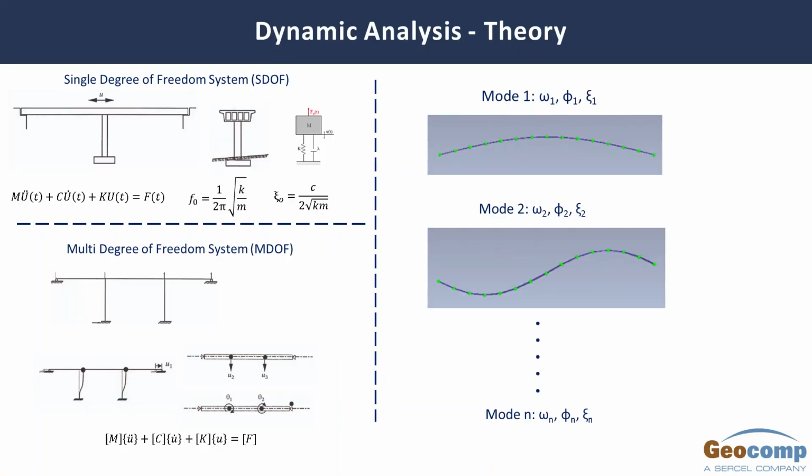So what we do, now we are going into the observation phase, the field testing phase. What we do is basically discretizing that multi-degree of freedom system into some equations that we can measure. I'm not going to bother you with too much mathematics here. What you need to know is that in that third equation, that C is what we measure, basically a matrix of measurements. Through the singular value decomposition of that signal, which is like if you have a linear system of equations, that's the way you basically solve this problem, through the singular value decomposition.